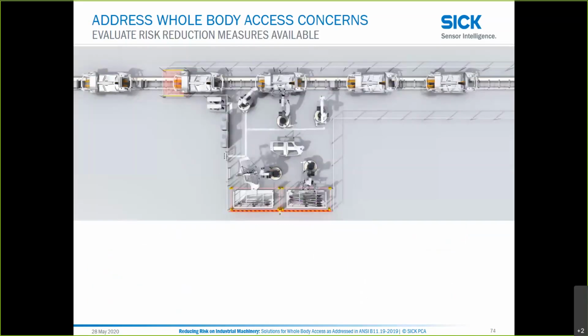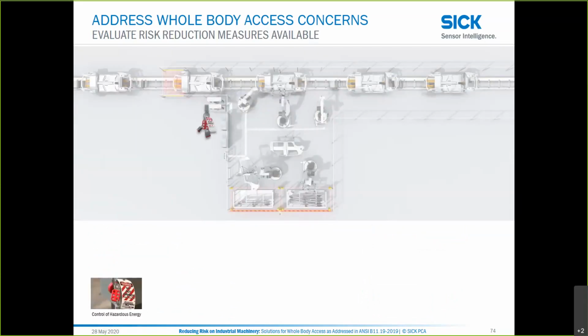So we start to go through this hierarchy of measures that can be applied. The first one is lockout tagout, if we can do it with controlled hazardous energy. For some tasks like maintenance, we don't need power available, so locking out is a great solution. Other tasks like setup, teaching the robots for instance, probably can't be done under lockout, so it may not be suitable for all tasks. We then go to the next option.